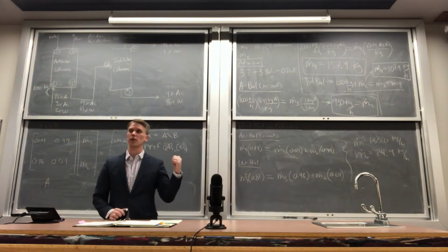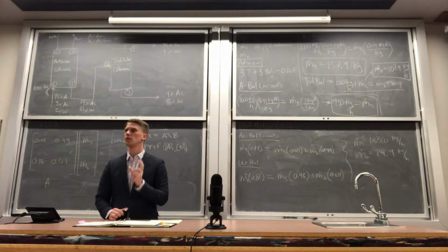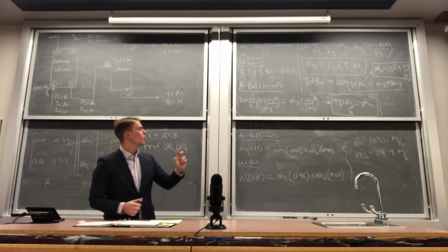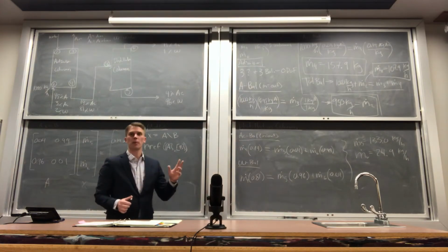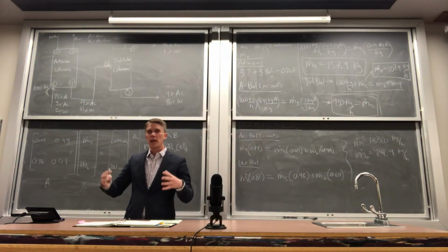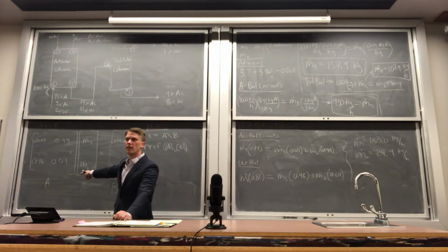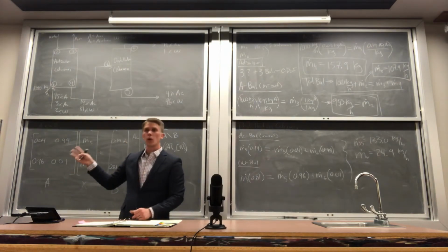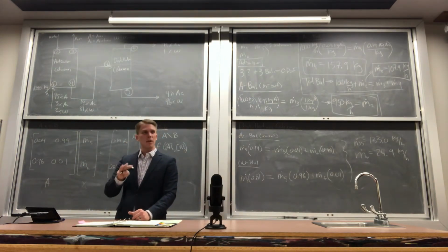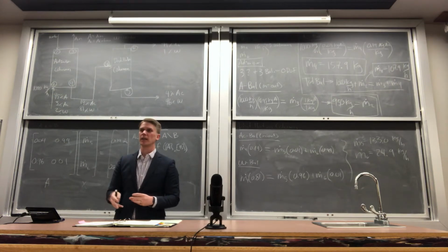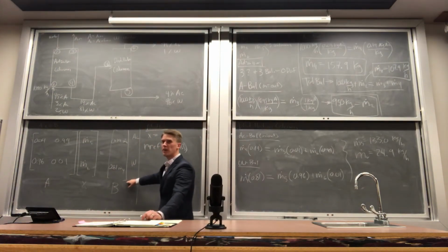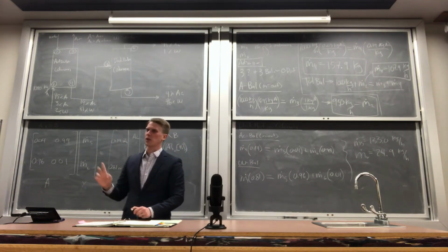These are all linear expressions. It's all adding and subtracting numbers. There's no multiplying and dividing involved of 2 variables. So in theory, we could have solved this entire system just by writing out 5 independent material balances, writing it into a big 5 by 5 matrix, and solving it. Now, if that seems easier, go ahead and do it. For an exam, it might make things a bit more difficult because I would say writing out a 5 by 5 matrix and getting all the math to line up well is a bit on the trickier side, right?